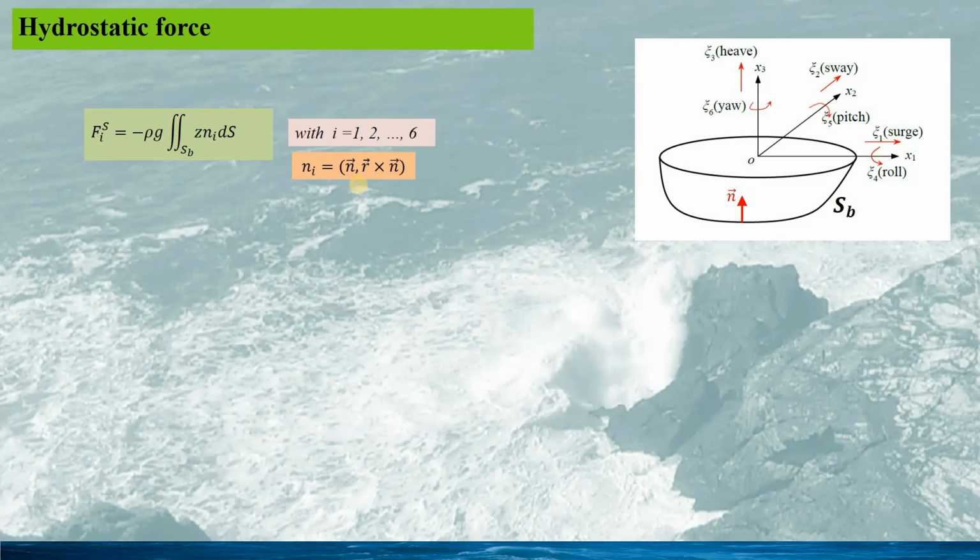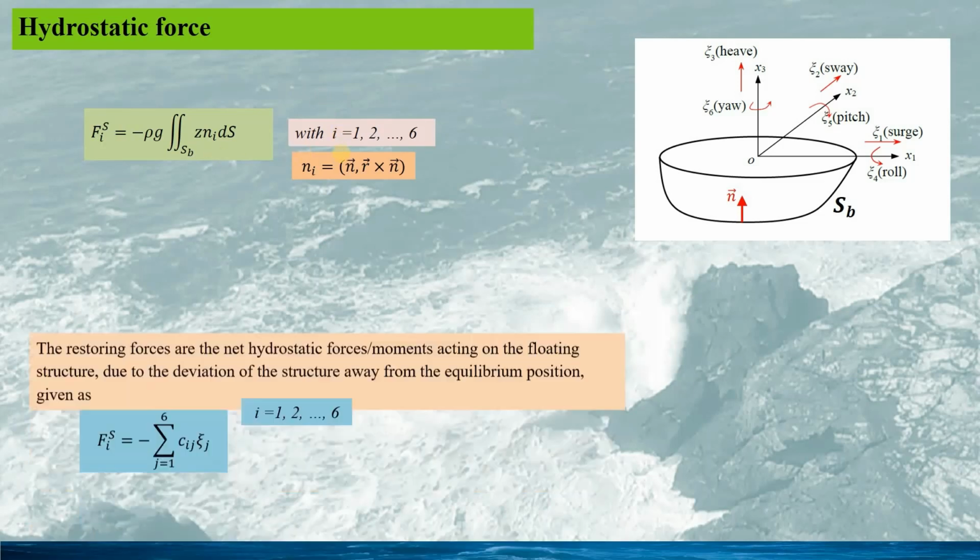These zero-order forces would be the largest for wave structure interaction, but they would be balanced with the structure weight in its equilibrium. For instance, in equilibrium position, the buoyancy would balance the structure weight for the freely floating structure.